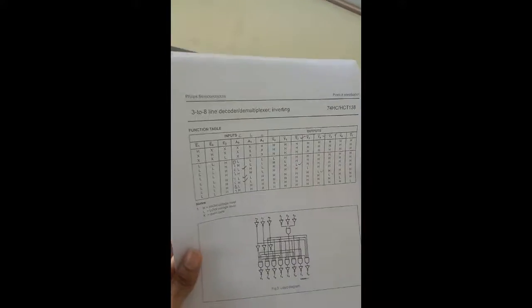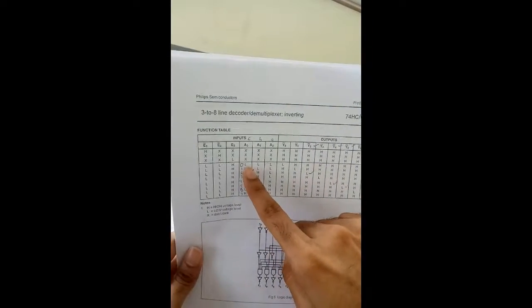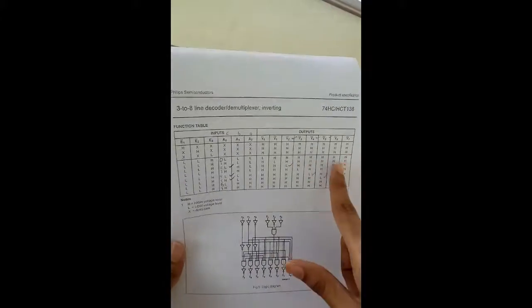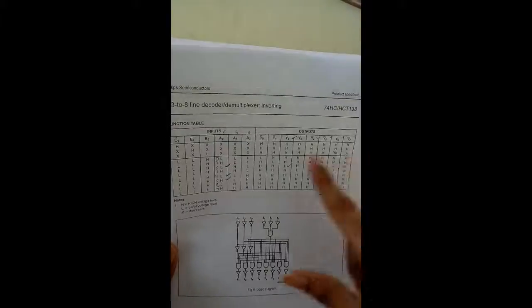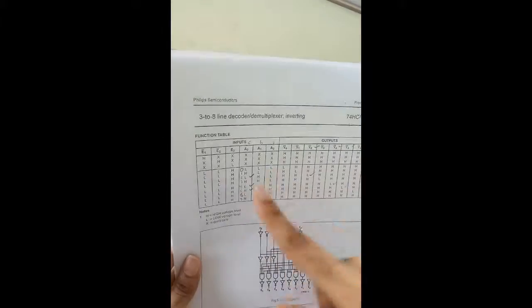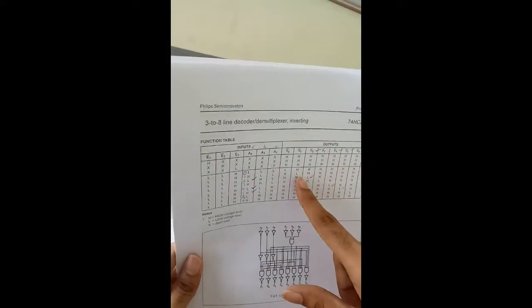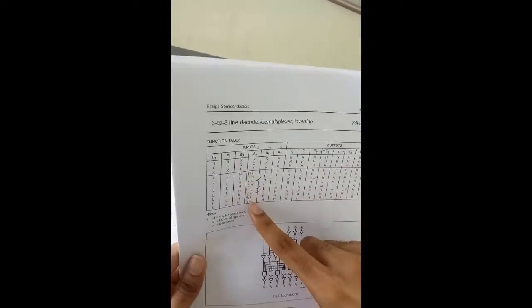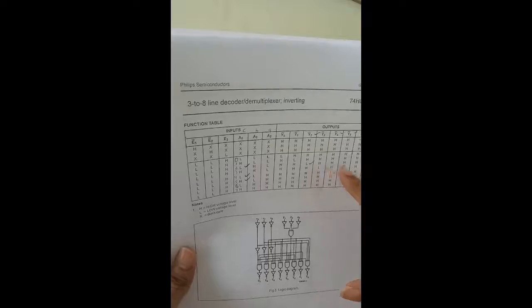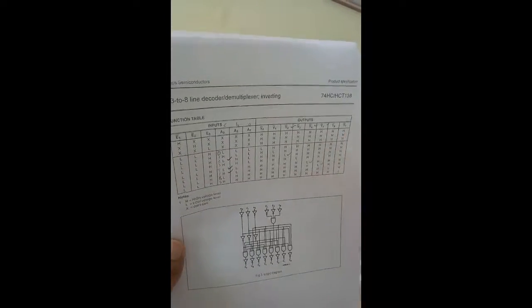Now, looking at the data sheet for the decoder, we can see that when the input is 0, which is low for the 3 inputs, the outputs are going to produce a high besides Y0, which is going to produce a low. But when the counter increases the number to 1, you can see that the second output is going to be low, and that carries on for every number that's increased. When it's 3, the third output becomes low. When it's 4, the fourth output becomes low. And you can see how the sequence occurs for a light chaser.